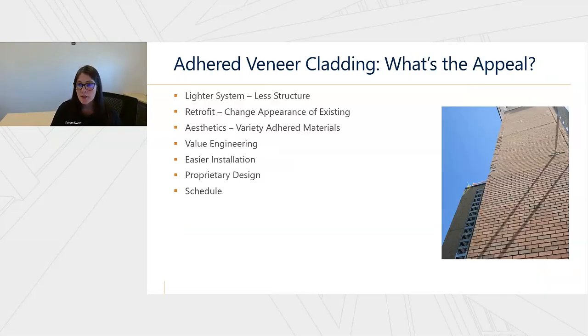So what's the appeal with these systems? We're seeing them more and more on the marketplace. They can be lighter systems. We require less structure to support them. In retrofit applications, we may be using these to change the appearance of an existing wall. The example photograph here is a precast where we're using thin brick to change the appearance of this exterior facade.